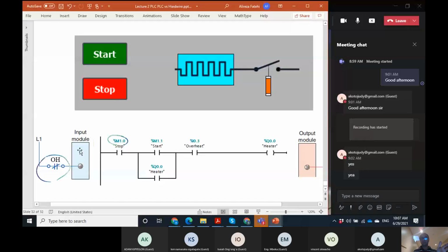All of them, or a big portion of them, can be indicated in the HMI. We don't need them anymore. So the number of input-output cards reduces, as do the size of the cabinet, the amount of wiring, wiring engineering, installation and maintenance. Although the HMI is expensive compared to one start-stop push button, if the number of input outputs is more than 10 or 20, generally the price of the project reduces significantly.